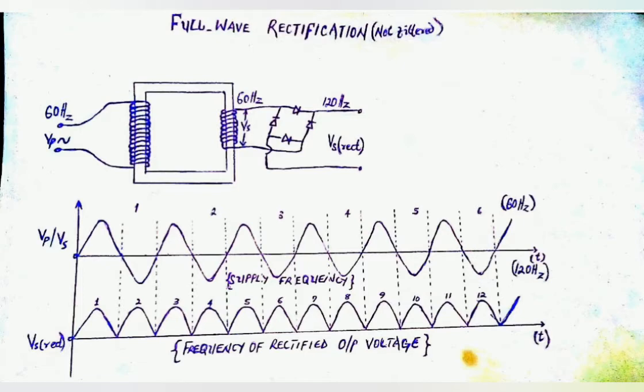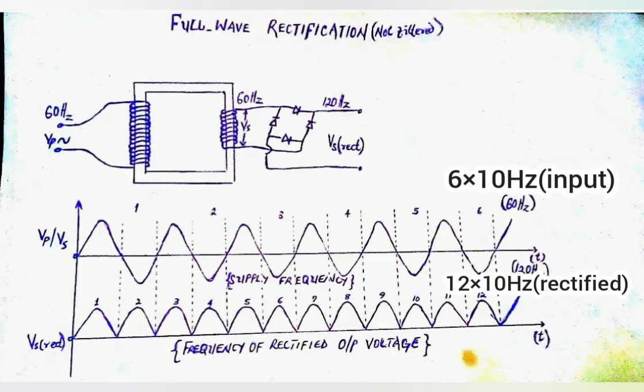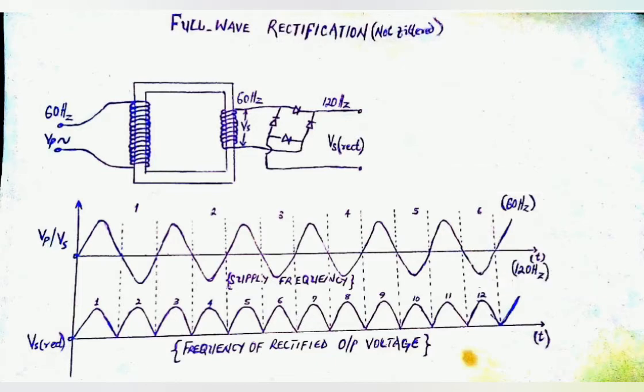Looking at the diagram, we can observe that 1. Current flows through the rectifier during both positive and negative half-cycles. 2. Just after rectification, frequency of the output rectified voltage is 2 times frequency of the input AC voltage. 3. The waveform still has some features of the AC waveform.